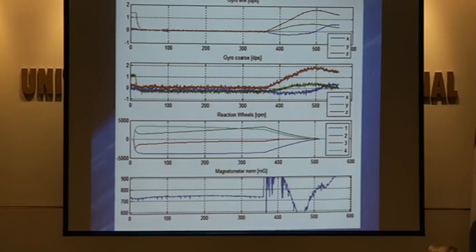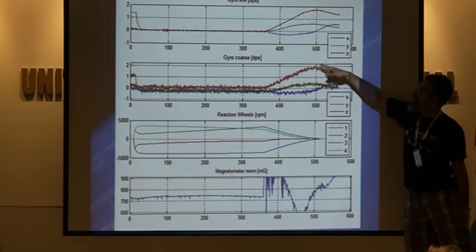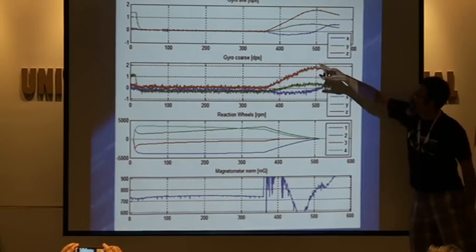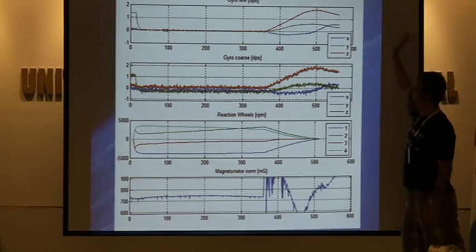And at this point, we turn on the reaction wheels. These are 4 motors that you control independently to make the satellite rotate or actually stay still. And this is the result that we downloaded from the experiment. This is the gyroscope with the angular velocity, and it's flat on 0 during the experiment. And then when we release the wheels, it comes back to the normal rate.